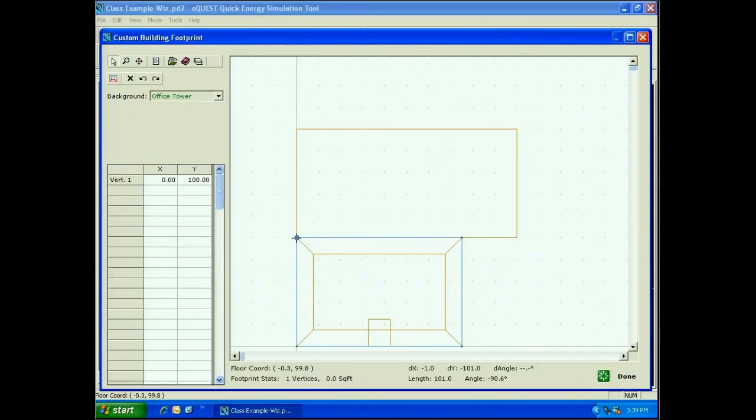Okay. Now, click on the arrow so that we can start drawing our dots. Click on here. For the next one, get it out to this corner, and up to that corner, and up to that corner. Again, we have to go counterclockwise. And since we have this CAD drawing in the background, you can see the first shell that we did, that office tower. And by tracing it this way relative to the office tower, it's going to put this shell right where we want it.